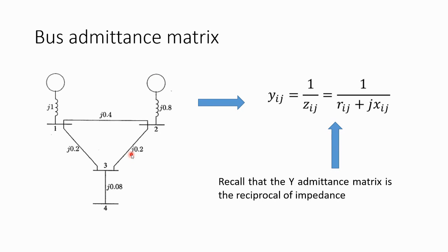This can be understood by analyzing how transmission lines and generators normally behave in a real-life network. In practice, transmission lines transmit power over a very long distance and power losses are kept to a very low level. If that happens, we can say that the resistance on the line is very low, and we can consider it as zero in our analysis. The same can be said for our generators.